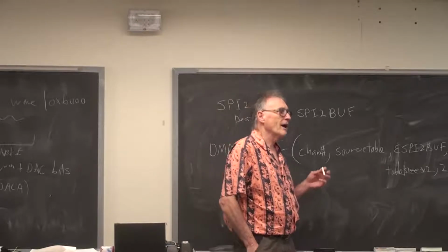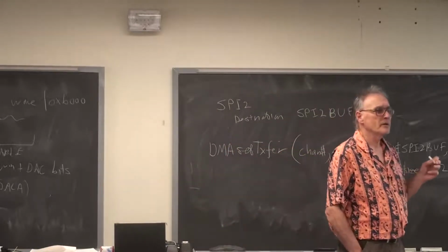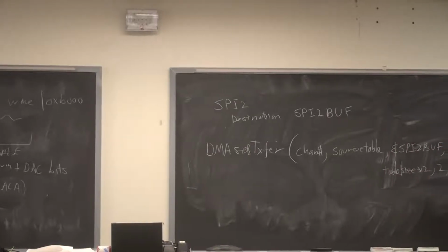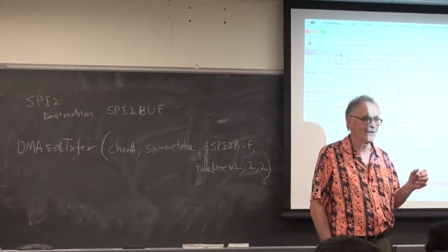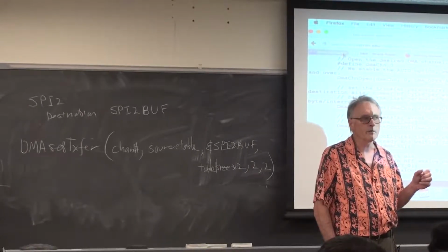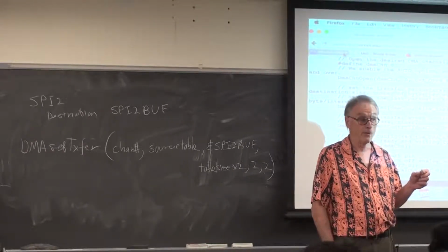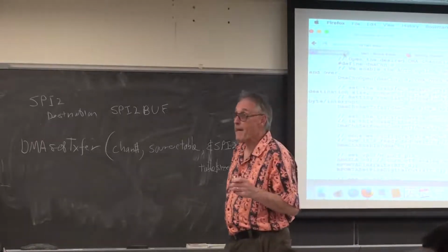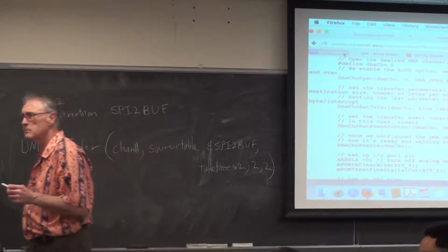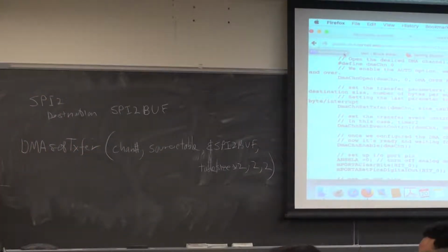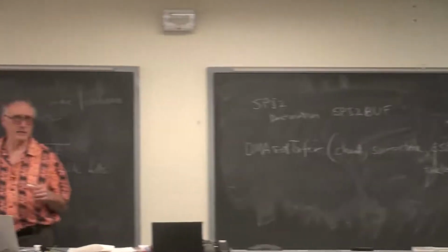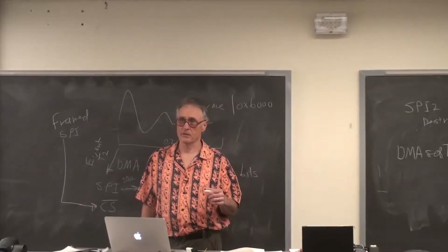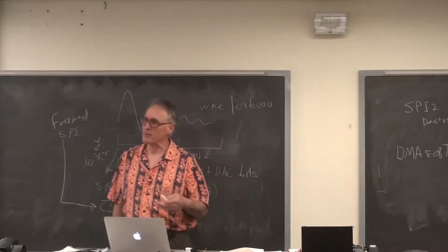How big a short int table can you build on this processor? How many bytes of RAM do you have? You better find out. How many bytes of RAM do you have on the CPU? This should be burned into your brain by now. It's 32K bytes. You might be able to use half of that for tables. There's got to be room for a stack and a heap and other stuff.